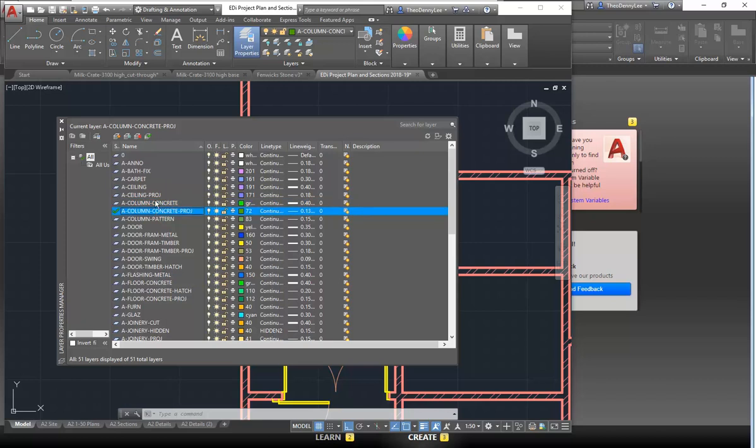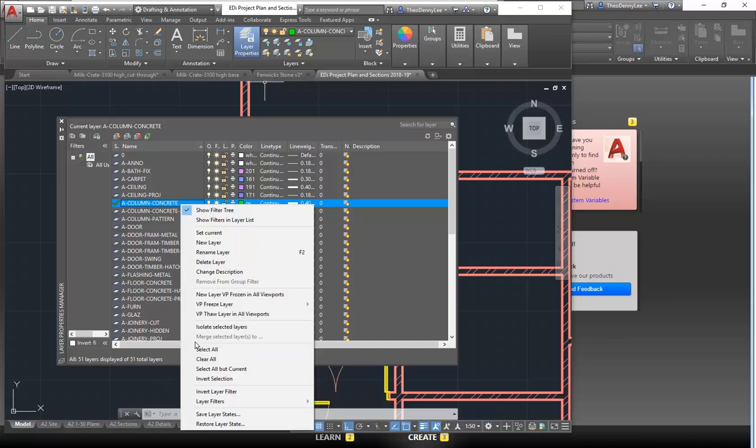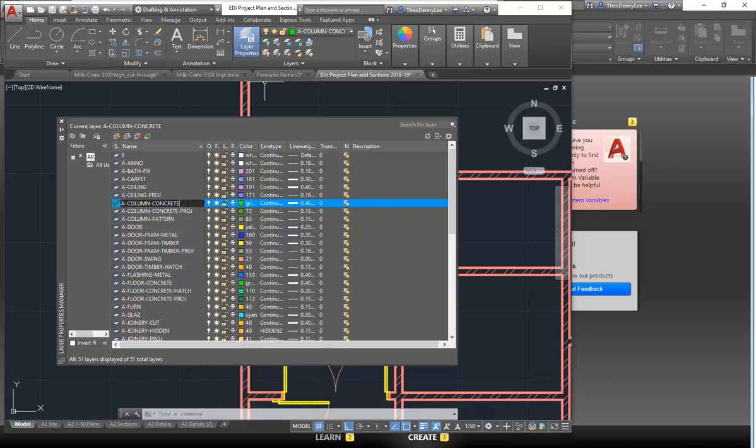So is it clear why you need those two layers for many of the object types that you draw? Exactly, that's it. That's right. So you can get two line weights for the same thing. And it's depending on whether it's in projection or whether it's cut, essentially. So if it doesn't say what it is, then usually you can assume it's cut. But there's no problem if you want to make it clear for yourselves, and I can do this myself. Put the cut in there, so that's clear.